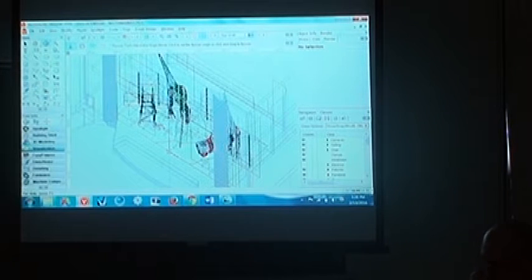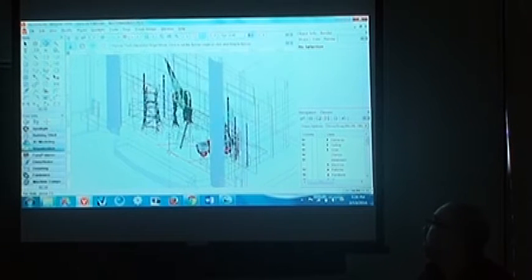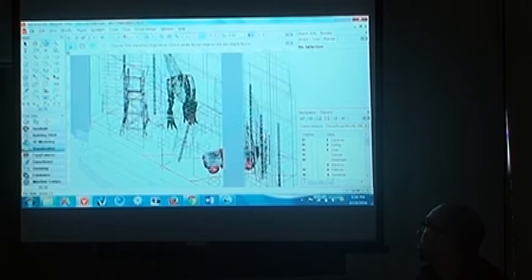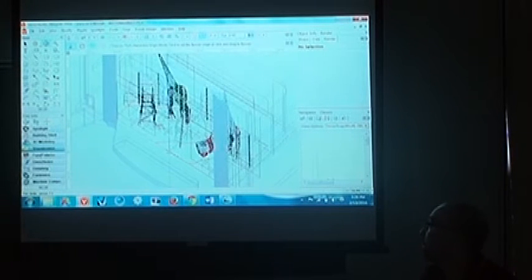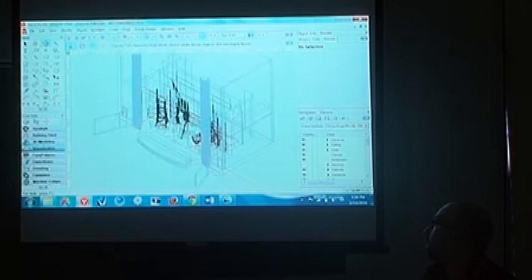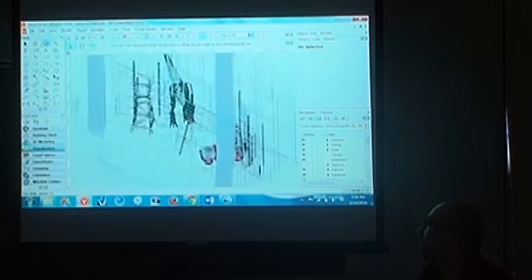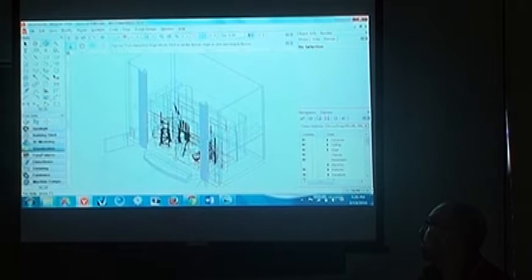Control-Shift comma and Control-Shift period will cycle through your views, forward and backward. It's basically next and previous. So it's a way of undoing your view changes only. If I change my view, I'm like, oh, I want to go back to the view I had 2 changes ago. I can just Control-Shift comma, and it'll go backwards.